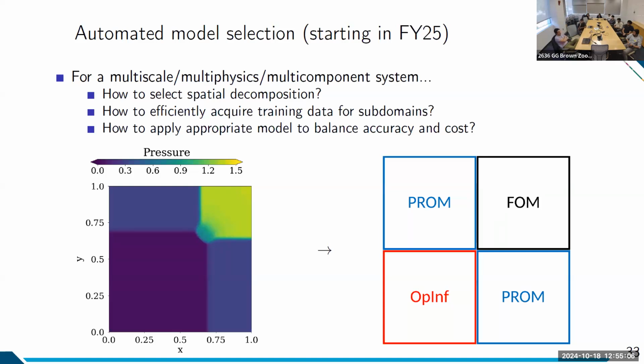For general guidance, you want to subdivide as little as possible, because subdividing more generally requires more Schwarz iterations to converge. In this case, we only chose a 2x2 decomposition because that's the minimum size required where you have waves propagating both in the X and Y direction crossing interfaces.